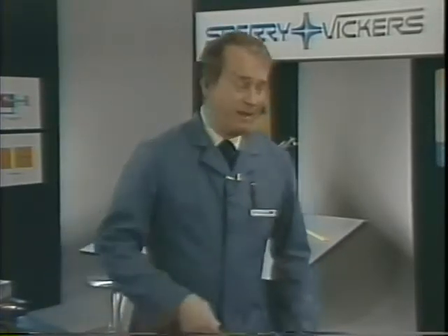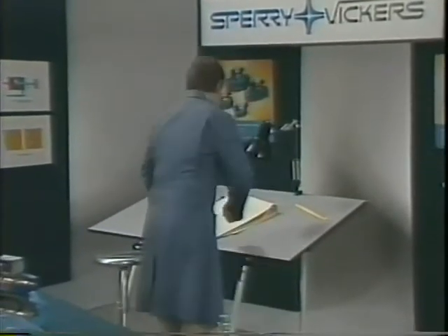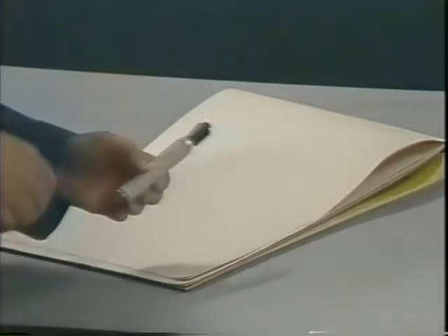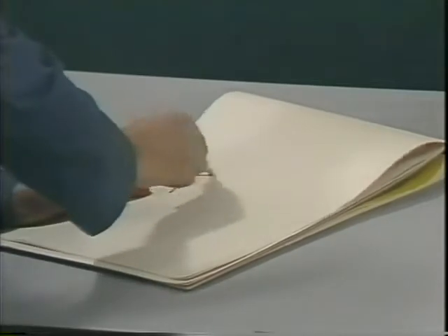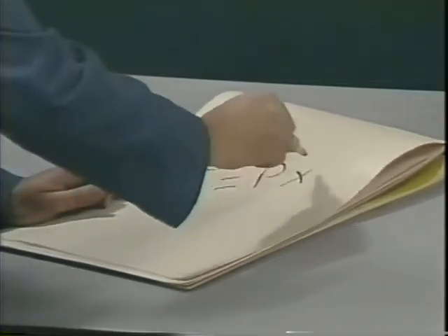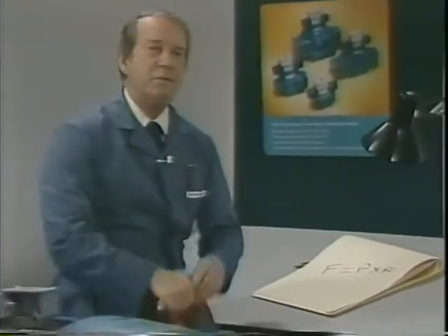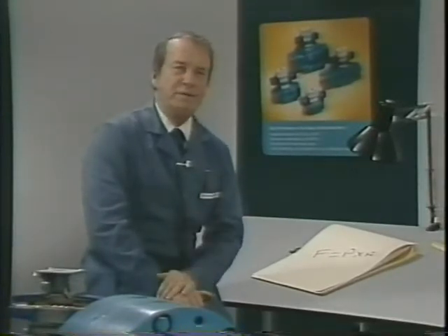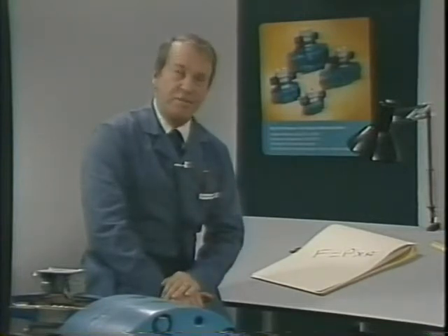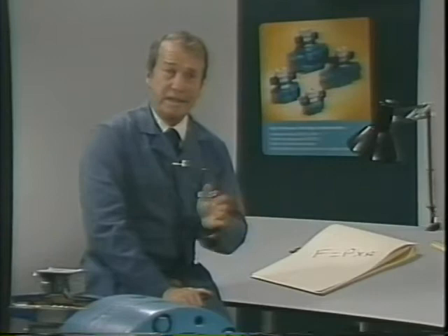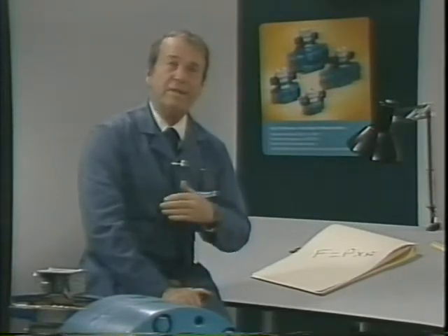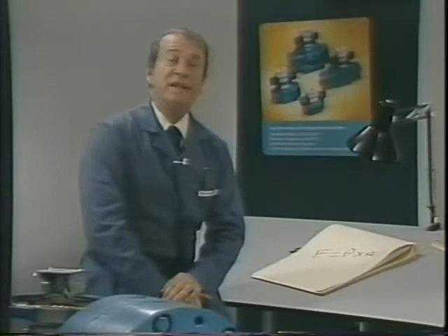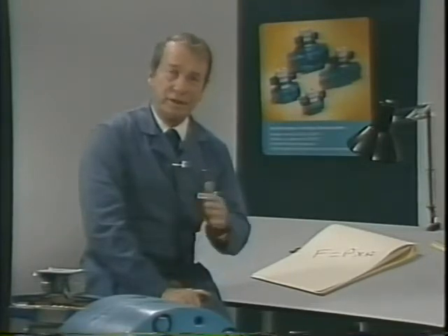A rod connected to one side of the piston extends from one end of the cylinder to the part to be moved. Now, here's another point to remember. The force exerted by a cylinder depends on its area and the pressure that's applied. Force equals pressure times area. Since the rod reduces the effective area of the piston, the force available when retracting the piston will be less than it is on the forward stroke. The rod, however, will partially fill the cylinder, so less fluid and proportionately less time will be required for retracting than for extending. Here again, what's gained in force is lost in speed or distance.